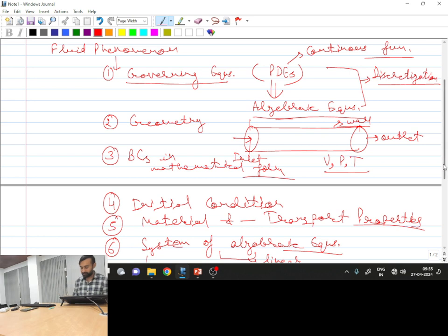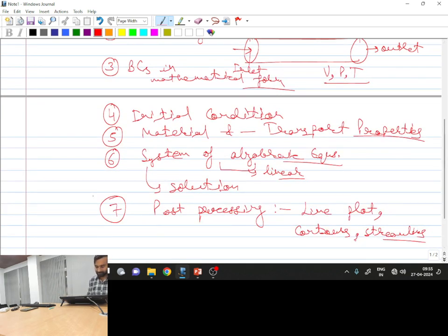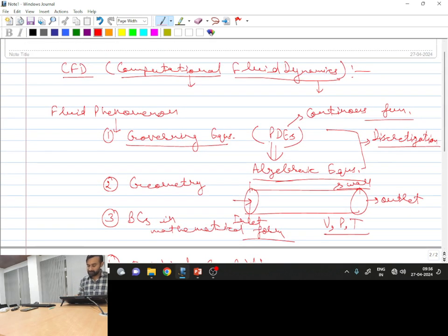a discrete solution. Whatever solution we obtain from CFD is not known at each and every point within the domain. It is known at certain discrete locations. Why? Because the process of converting partial differential equations into a set of algebraic equations utilizes discrete locations to represent derivative terms as algebraic difference equations.